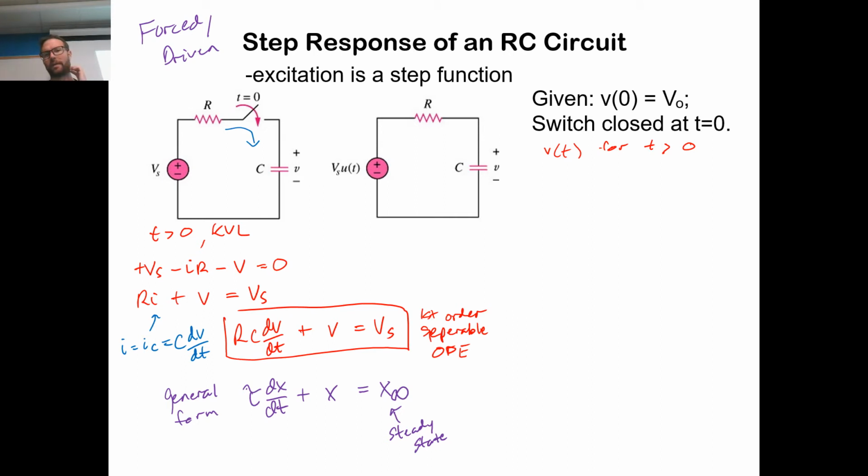I think I do it before deriving it, but before we even do the derivation, let's just talk about the fact that this variable, Vs, is the voltage at t equals infinity. Eventually at t equals infinity, the capacitor fills up with charge. No more charge can come onto the plates, so the current drops to zero.